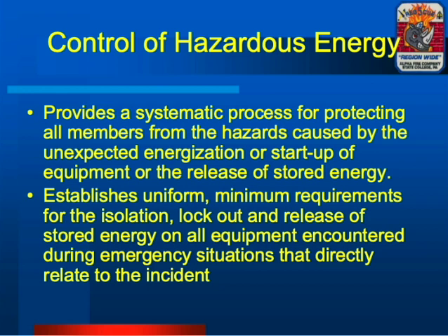With any policy or procedure, or any standard for operating, this is going to give us minimum requirements of how to isolate, lock out, and then release any types of stored energy. We may generally find this on rescue operations that involve elevator rescues. So we might need to control the power or the hydraulics for the elevator. This may also come into play for industrial rescues. If you're working in some sort of industrial facility, this may also come into play. Even think of the basics of a vehicle accident, where we want to disconnect the battery and isolate the hazardous energies.